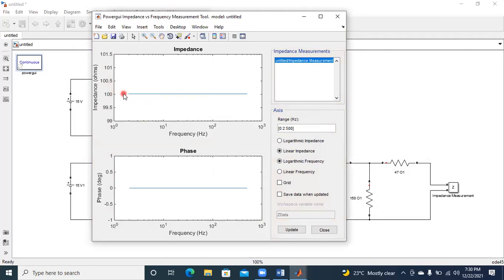The impedance value, the Z value is 100 ohms and the phase difference is 0 degrees. So when I say that the phase difference is 0, can I go for the resistor? Can I say that this is the resistance? So the Z impedance is nothing but 100 ohms. For example, if it is 90 degrees, I can say that it is either an inductor or capacitor based upon the lagging, I mean, plus 90 or minus 90. Okay, so fine.